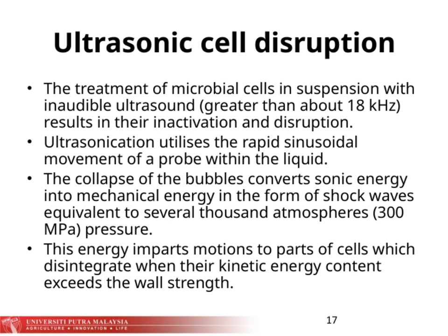When these bubbles collapse, they convert the sonic energy into mechanical energy. Think of shock waves, which can reach pressures of several thousand atmospheres, around 300 MPa. This intense energy creates powerful motions within the cells. If these motions, what we call kinetic energy, are strong enough to overcome the cell wall's strength, they cause the cells to disintegrate.